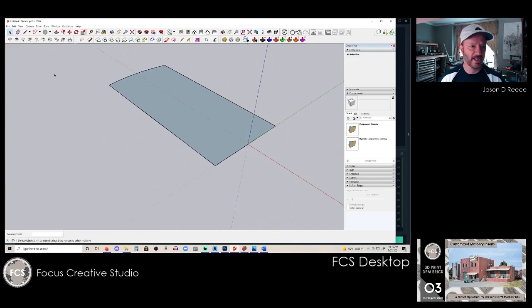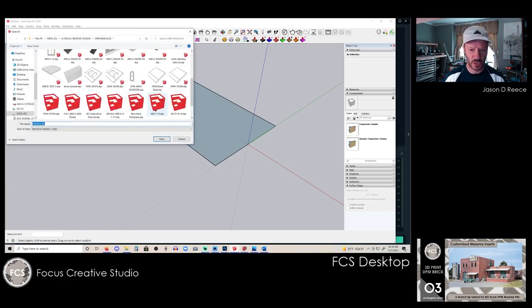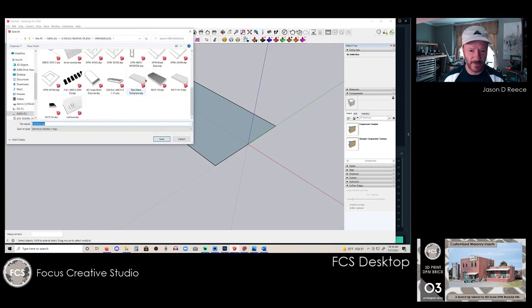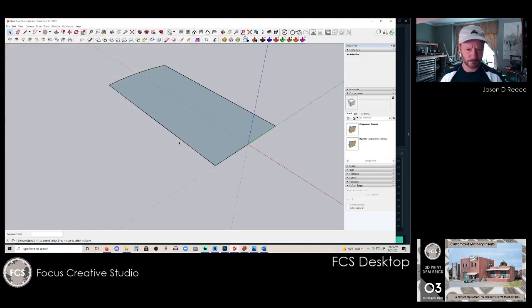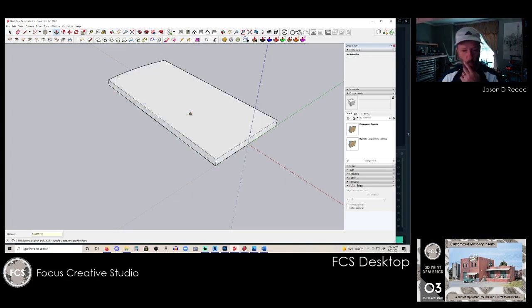And I'll just go ahead and save this file, save as, and we're going to go down here. I've done this before, but I want to go ahead and override this because we're just basically creating everything from scratch. So save that. Yeah, we'll override that. I'm good with that. All right, so now I've got depth to this. I have a portion of the base that slides into the insert, which is 1 millimeter tall. So I'll push pull. I'll pull this up 1 millimeter, 1 enter.